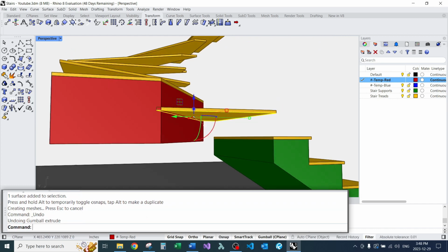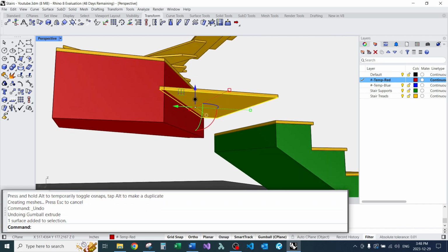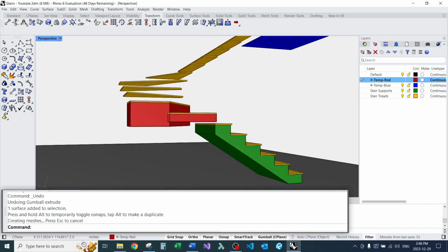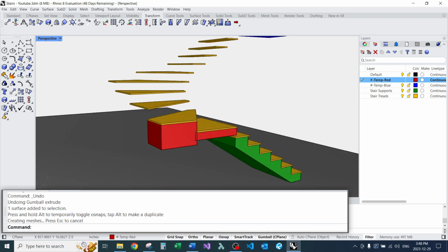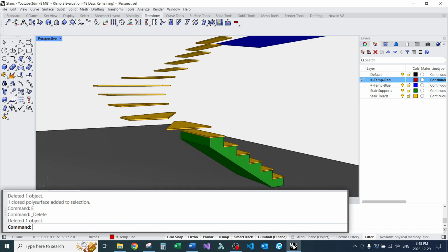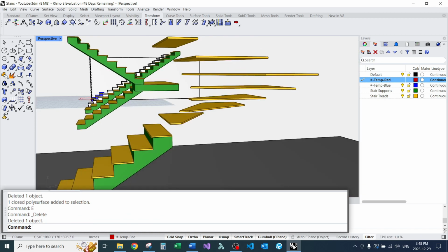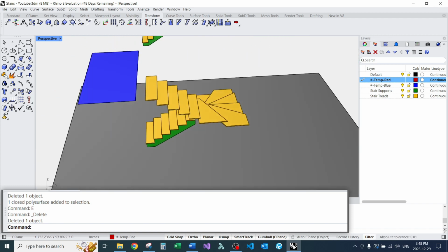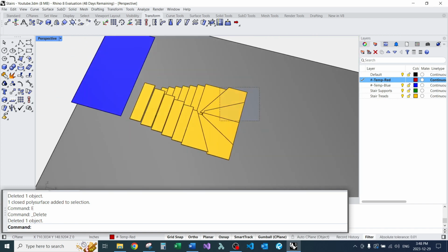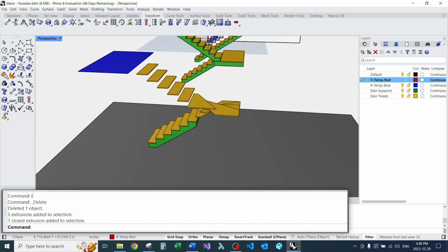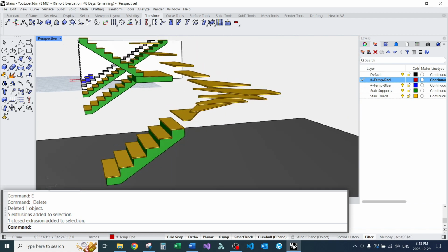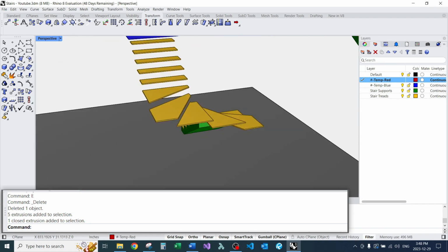I'll just take a quick second to mention that when you frame underneath your winder stairs, I think that's a big case for doing them in Rhino. If you figure out what's underneath here, if you can just fill up underneath the winders with framing, that's the easiest to build, but you end up with a lot of void space.